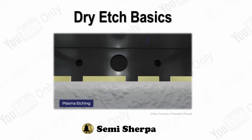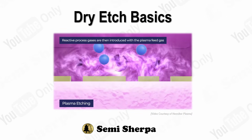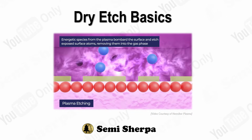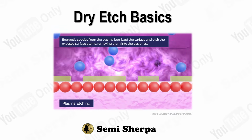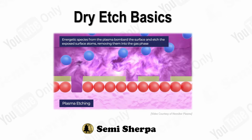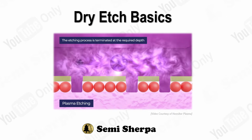Part 3 focuses on the outputs you must analyze during and after etching. We cover process responses such as etch rate, selectivity, and etch amount. We also cover pattern transfer metrics such as repeatability, uniformity, etch target, loading effects, and plasma-induced damage.